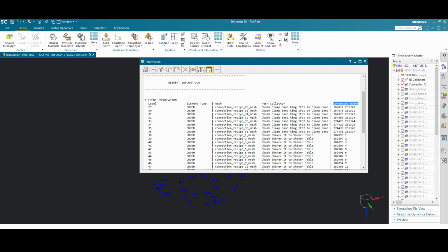And finally, connected nodes, which contains the IDs of the connected nodes of each element. The user should pay attention to the axis of the coordinate system along which a bolt is positioned, x, y, or z. This influences the axes along which the axial and shear forces of the bolt are reported. Mars is designed to be extended to allow importing information produced by any finite element analysis software, and we can address this according to the user's needs.